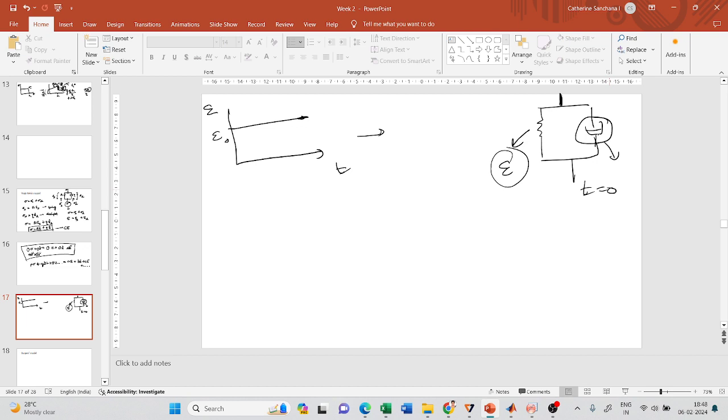Okay. So in case of a Maxwell model, it was not a problem because at time t equals 0, even if the dashpot took time to respond, it cannot deform immediately at time t equals 0. That is why at time t equals 0, the deformation of the entire Maxwell model was only due to the spring. But in the case of a Kelvin model, this will immediately deform. But the dashpot, which is parallel to it, will take a lot of time to deform.